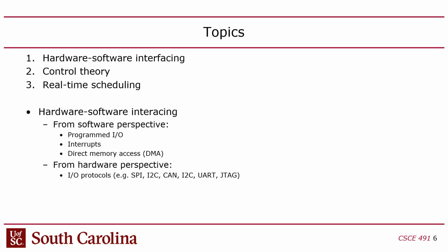So you end up with all these different tasks, some of which are operating at different control steps. So you have a mixture. They're not all at the same period. They're operating at different periods. And so that becomes a challenge to guarantee that your processor won't blow any of the deadlines, any of the performance constraints you have for the system.